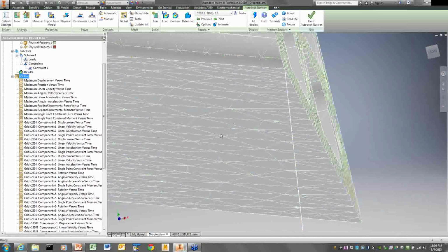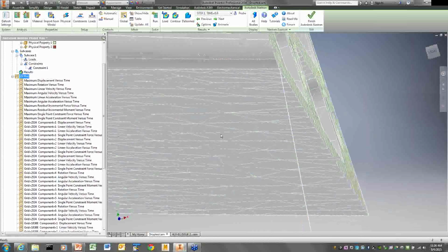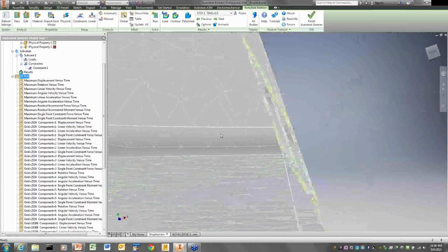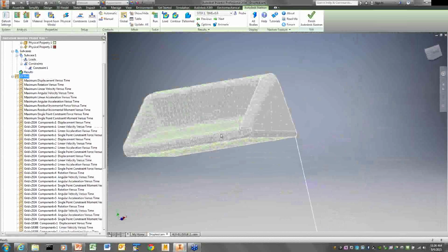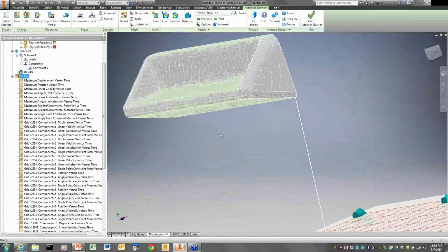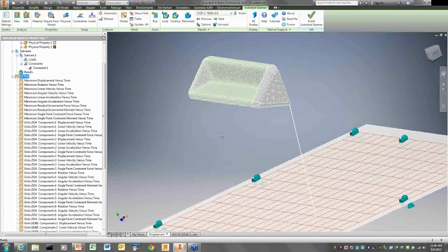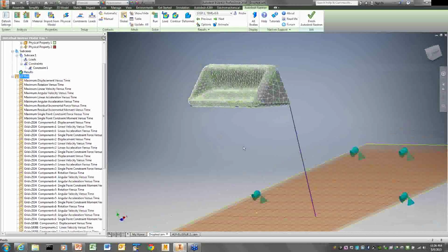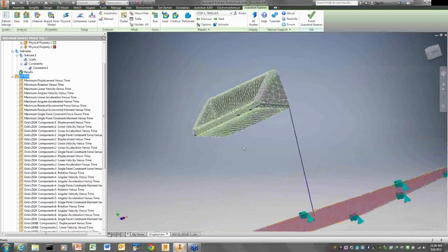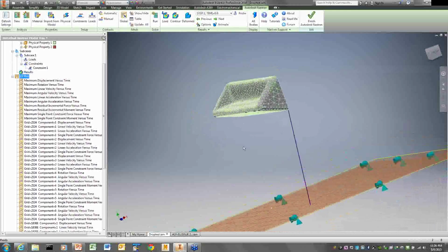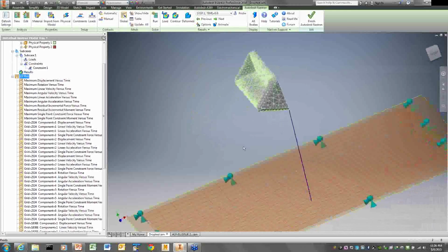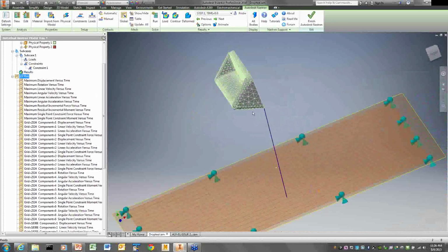Okay. Well, to interject something there real quickly, if I recall correctly, if you were to perform a fast Fourier transformation on that, you could actually extract the natural frequencies of the model. Absolutely. What it's vibrating at, that noise is the natural frequency of the structure itself. Absolutely. And depending on what kind of damping you've put into this analysis, you'll be able to see the high frequency and the low frequency ones, and you'll see high frequency things often damp out faster. So you'll see a lot of high frequency noise that'll get smaller and smaller,